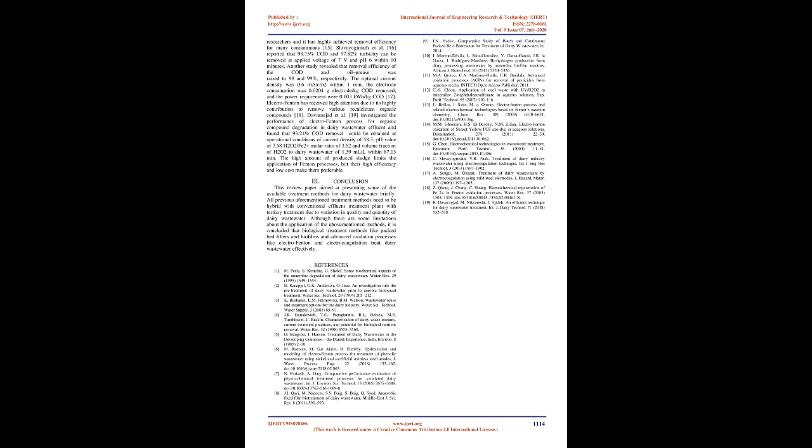Conclusion. This review paper aimed at presenting some of the available treatment methods for dairy wastewater briefly. All previously aforementioned treatment methods need to be hybridized with a conventional effluent treatment plant with tertiary treatment due to variation in quality and quantity of dairy wastewater. Although there are some limitations about the application of the above-mentioned methods, it is concluded that biological treatment methods like packed bed filters and biofilms and advanced oxidation processes like electro-Fenton and electrocoagulation treat dairy wastewater effectively.